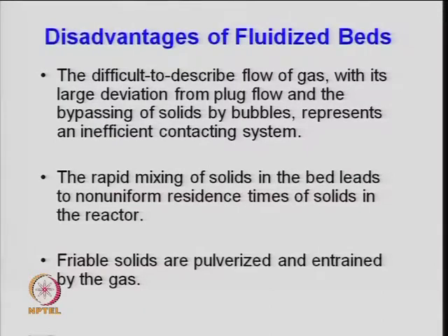It is very difficult to describe the flow of gas, with its large deviation from plug flow. As I said, the fluidized bed reactor generally behaves like a CSTR, a mixed reactor, right. But with a CSTR, the conversion will be low, and when conversion is low, the productivity will be low. So, we want a more plug-flow type design. It means you need higher velocity, higher severity of operation, right. So, maintaining plug flow condition is difficult, right.